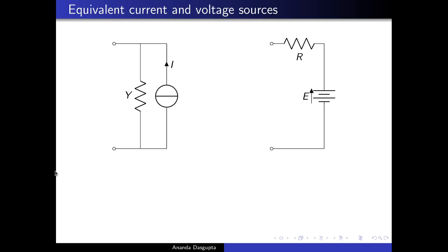So how do you model that? Well, you model that by a very similar trick as the one which we used here, you model that with a current source, an ideal current source. This is one of the symbols used for ideal current source, the one I'm going to use in this course, a circle with a line drawn across it. The ideal current source would have delivered current I to the external circuit if it were the only thing in the effective circuit. But the effective circuit to a real current source is an ideal current source connected in parallel to an admittance. An admittance, of course, is a resistance whose value is being measured in reciprocal units. So this Y is inverse resistance.